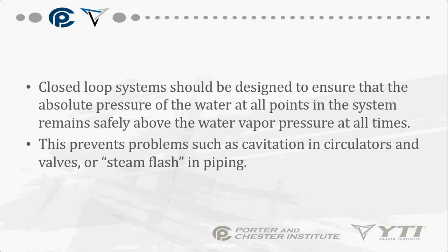Another way is also by having too much heat. You're overfiring maybe your burner, because adding too much heat can also raise the pressure inside a boiler. Your boilers are pressure vessels. We may not think 10 psi, 15 psi is a lot, but in reality, to water and water movement, that is a great deal of pressure. We don't want that stuff to rupture.